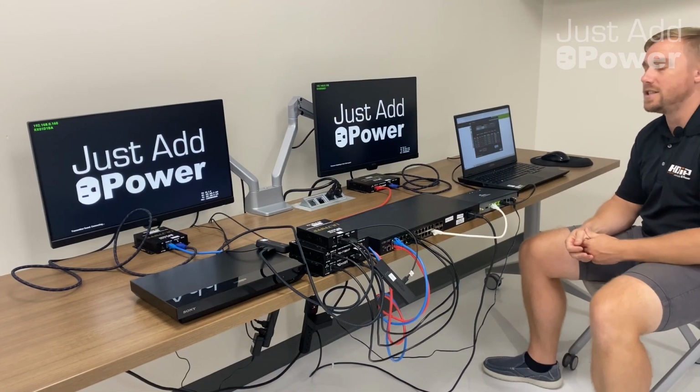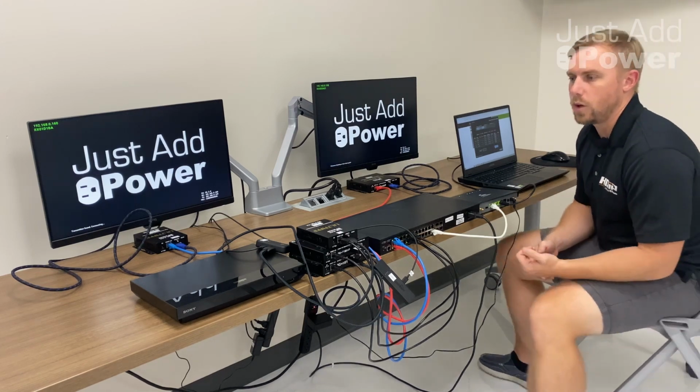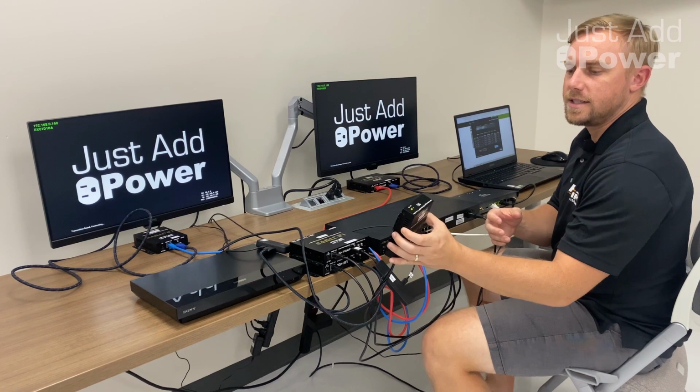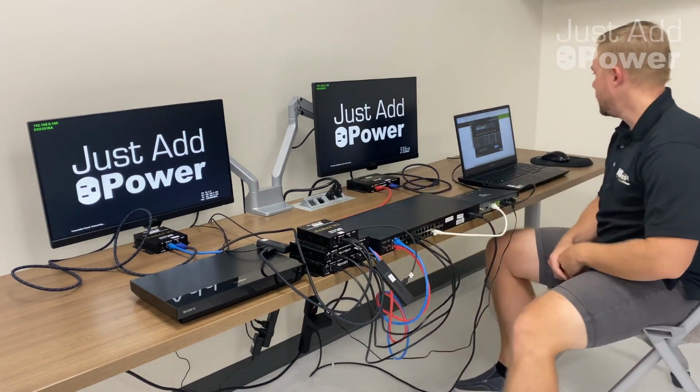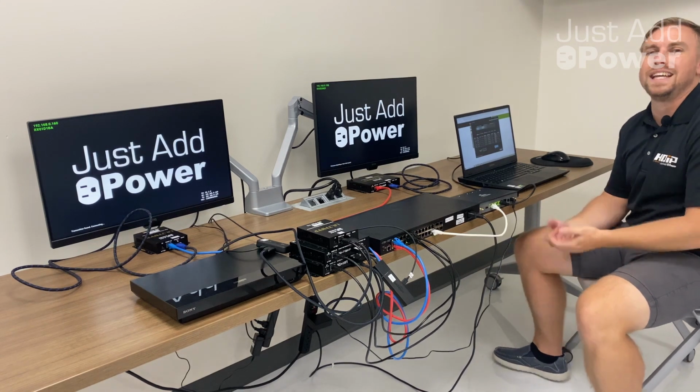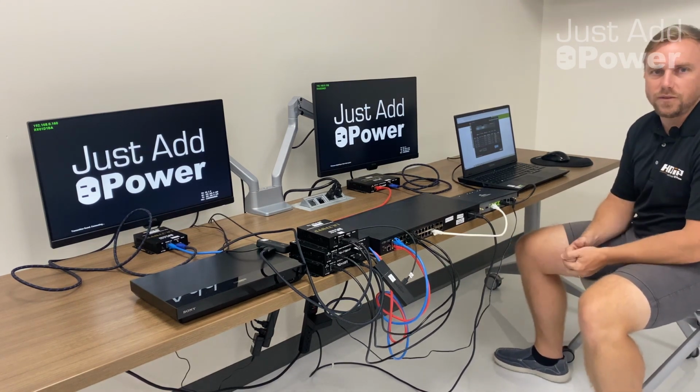If some of my devices weren't found, I would want to check those devices to make sure that all of them have a solid power and no data light at this point in the process, or a solid power blinking data light. That would indicate that they're ready to be discovered.